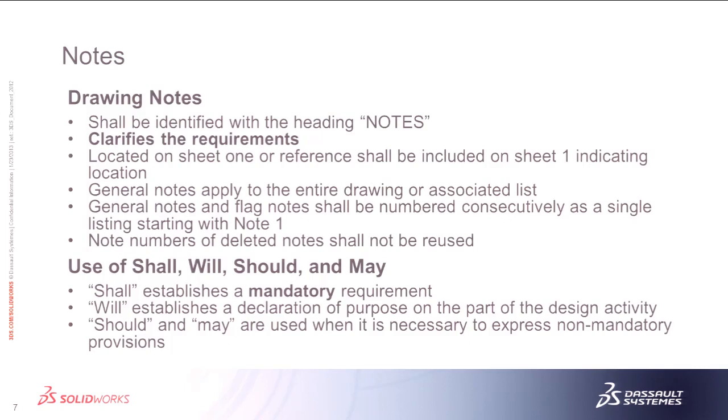So to start with, this isn't one of the fundamental rules, but these are rules. They talk about notes in the standards. It's very simple. We don't really care how you format your notes or stuff like that. That's not really covered there. But some of the things that should be included in your notes should include a header that said NOTE, all in capital letters. I think most of us know that the only time you can use lowercase letters is if you're going to put a millimeter, mm, next to a dimension to specify that it's millimeters. Everything else should be in capital letters on your drawing.